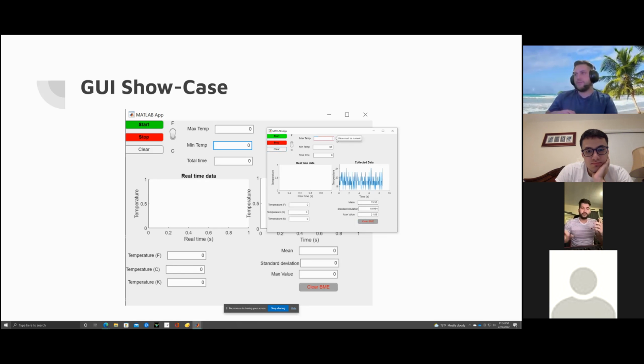So what I'm going to do is lower my top threshold to 65. And my minimum, I'm going to put it on 50. Now, every temperature should be above 65, so it will look red. Let's see. There we go. It looks red, and whatever is below 65 will look black. That's exactly what we wanted it to do.